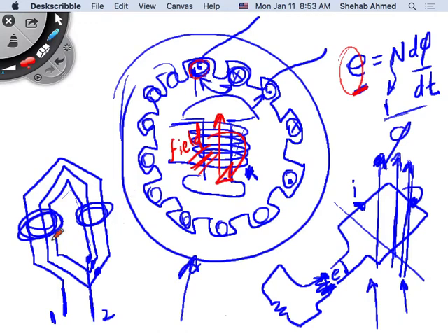Moral of the story is these are insulated wires. You cannot make them at 400 kilovolts. For you to make two wires that are close to each other at 400 kilovolts, we said the breakdown of 1 centimeter of air is 30 kilovolts, right? So 400 divided by 30 is what? 9, 8, whatever. 7. So I would need to make sure that I keep each wire 7 centimeters apart from the next one,